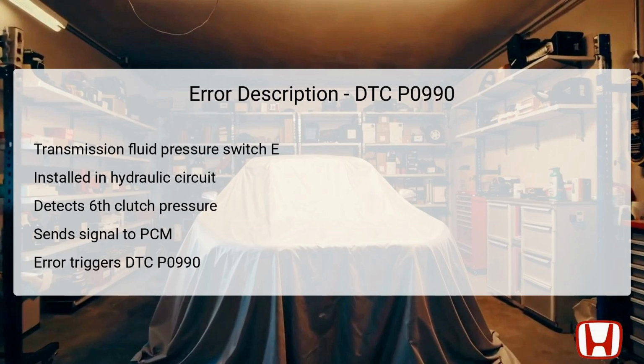It is strategically located within the hydraulic pressure circuit, acting as a sensor to monitor the pressure applied to the clutch. When the hydraulic pressure is applied correctly, the switch sends an on signal to the powertrain control module, PCM, which manages the engine and transmission functions. If there's insufficient pressure, the switch remains off, indicating a potential malfunction. When the PCM detects inconsistencies in the switch's status while the vehicle operates in 6th gear, it records the high signal state as a fault, hence triggering the DTC P0990.